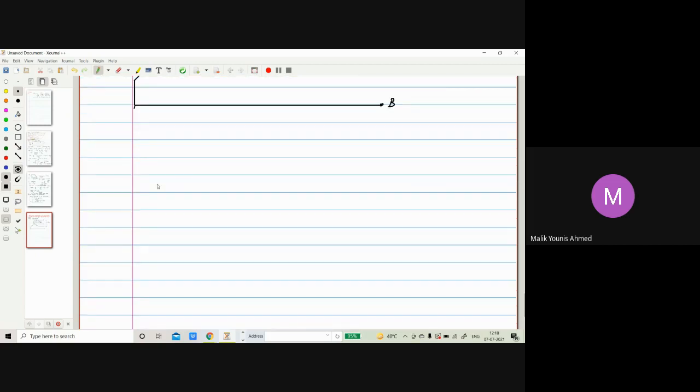Those are the basics. So let's move to the second type of connection we have. Next is delta connection. So this is a delta connection. Let me draw the delta connection again. Now delta connection, you can see it's like this. The finishing end of one phase is connected to the starting end of another phase. Then that is repeated for all the three phases.